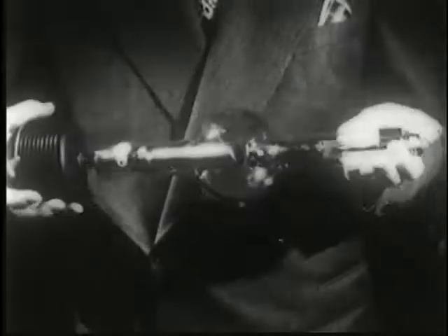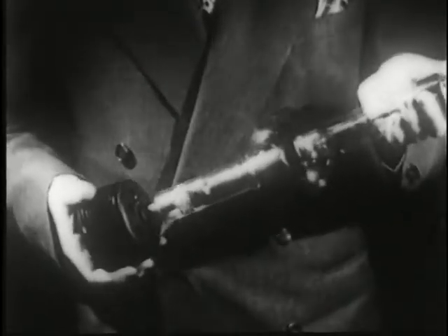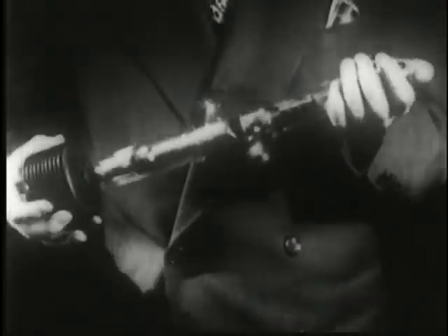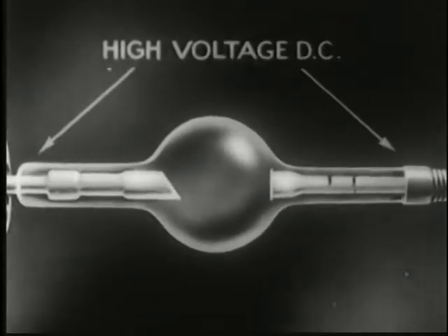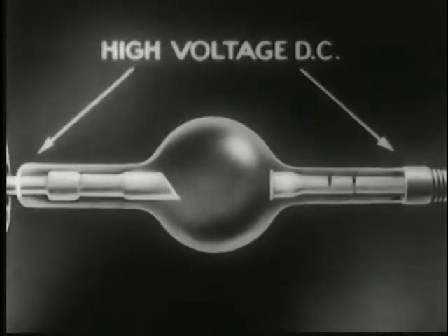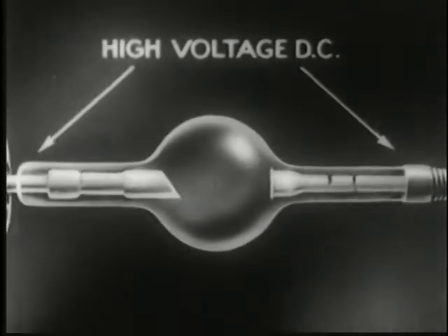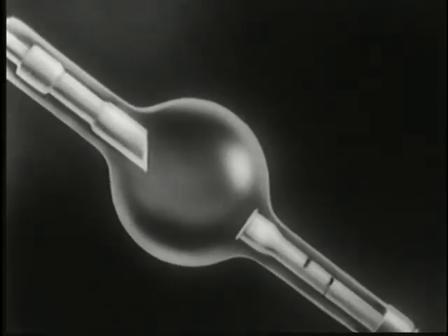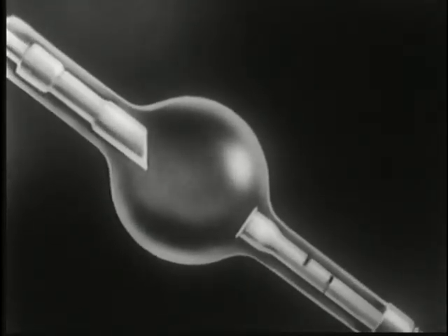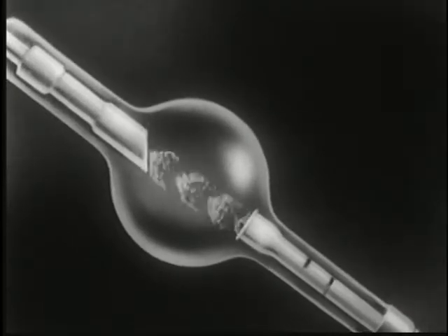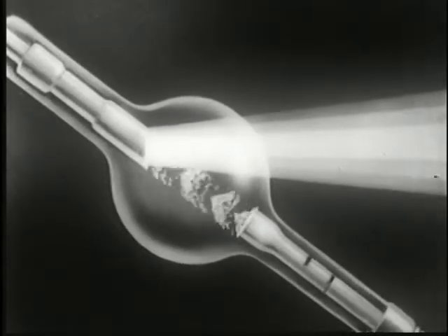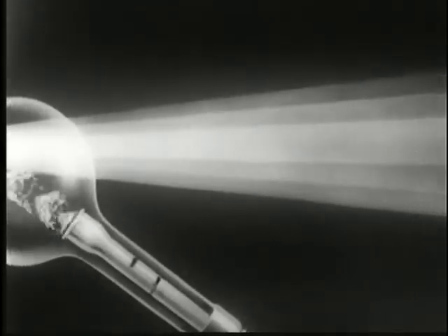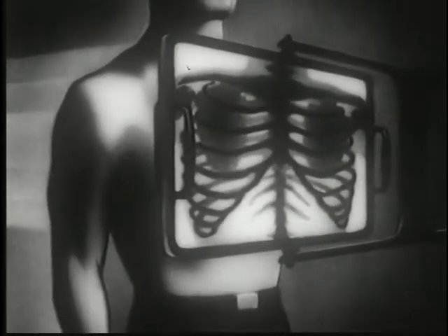The electronic X-ray tube indirectly also transforms electric current into light, and by its effect on photographic plate, into light images. Here's how an X-ray tube works. A high potential ranging up to 300,000 volts or more is applied between the anode and cathode. Electrons are emitted by a focusing cathode. Due to the extremely high voltage, the electrons hit the anode with tremendous impact and cause the emission of waves of exceptionally high frequency. These high-frequency waves do three useful things: penetrate, excite fluorescence, or affect photographic plates.